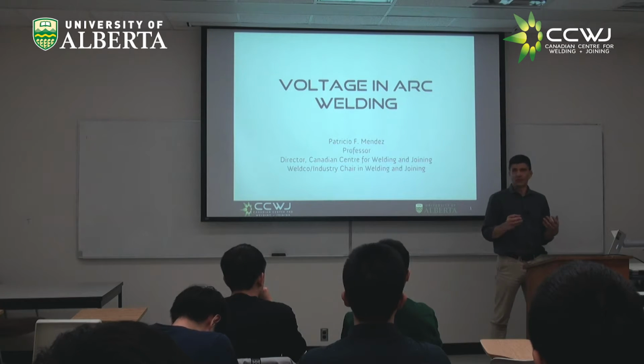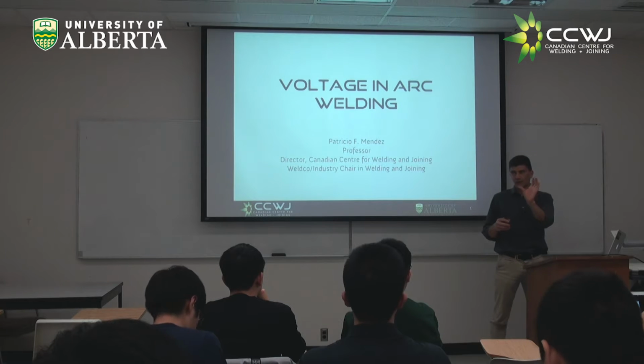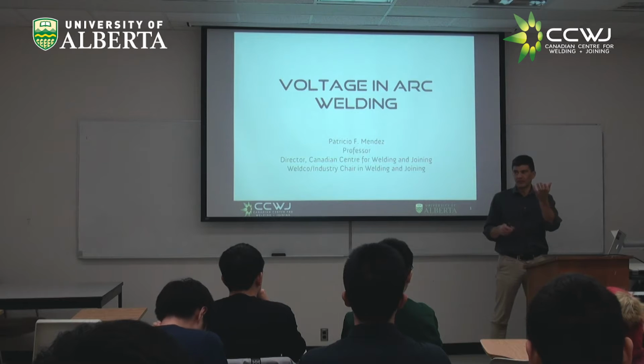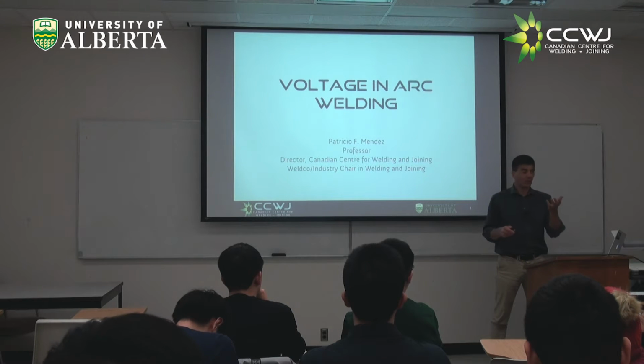So, for example, if we were to flip the polarity in MIG, right now the anode that was having 5 volts more or less, now is 14 volts. Do I melt more wire or less wire? A lot more wire, right? So those are the type of things we discussed intuitively.